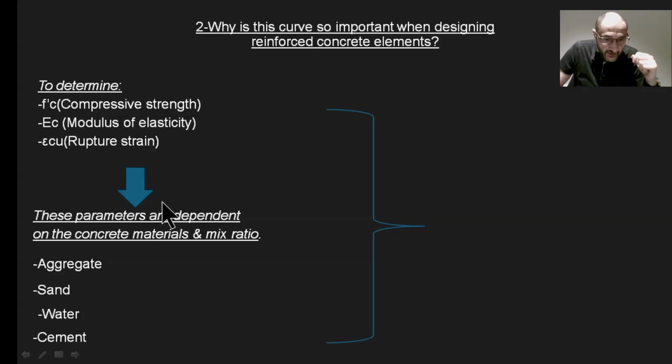The water cement ratio is very important, and that impacts the concrete strength, and it should be kept to around 0.5 to 0.55. Again, this will ensure concrete workability without affecting the strength. I'll show you a table later on with the relevant water cement ratios and all the other mix ratios of aggregate, cement, sand, and water. We'll go through it in the next couple of slides.